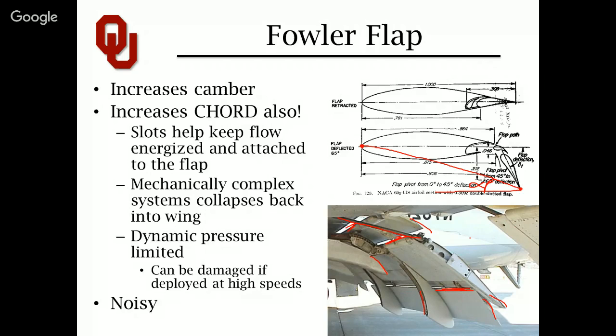You don't have to lift the nose far, far, far up to generate high coefficients of lift. And you saw in some of the other charts, these CL max values aren't reached until 20, 25 degrees. People would be concerned, to say the least, in the cabin if your commercial airliner tipped up to 25, 30 degrees to land. Not to mention your gear would have to be taller, the angle of retraction on the back of the fuselage would have to be more steep. It would just have many impacts.